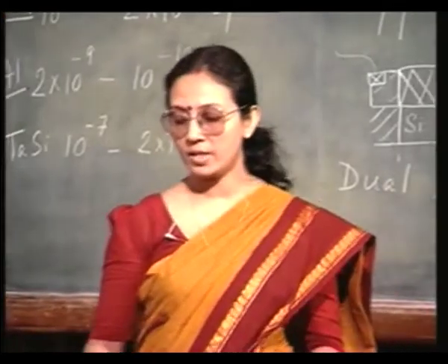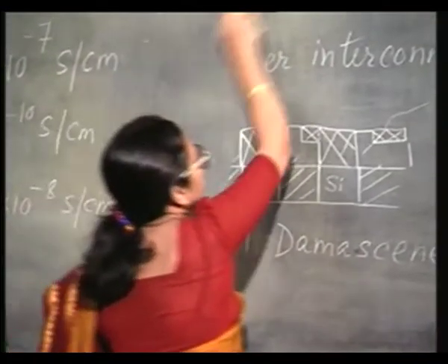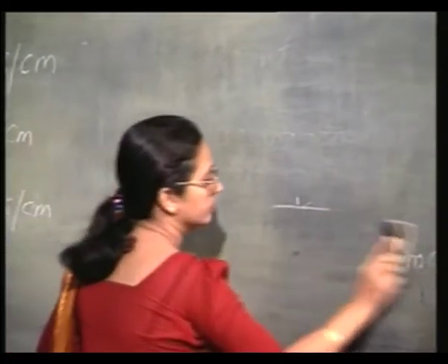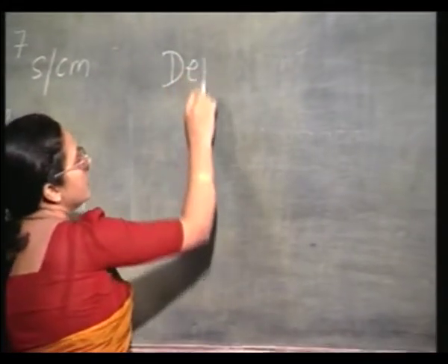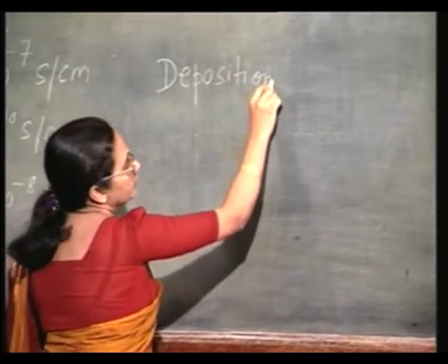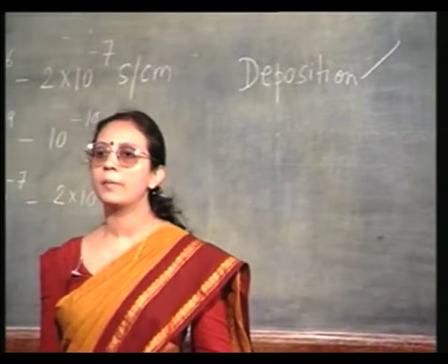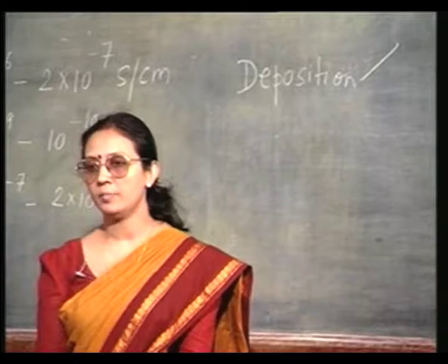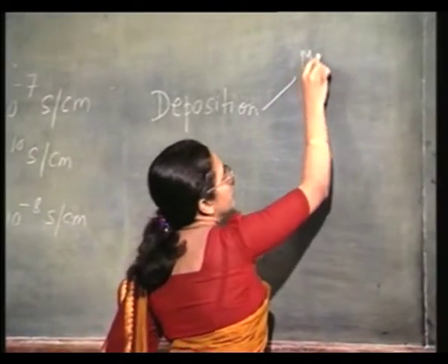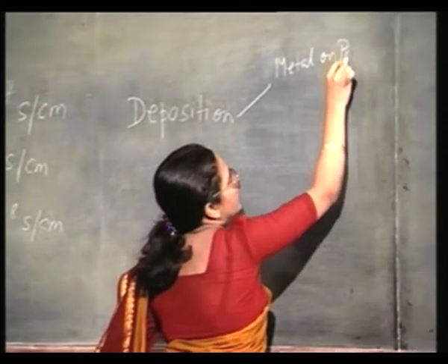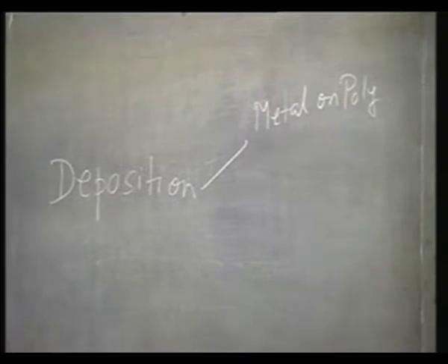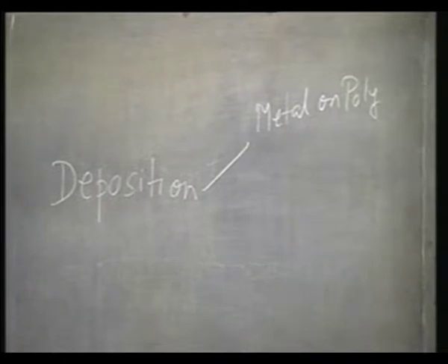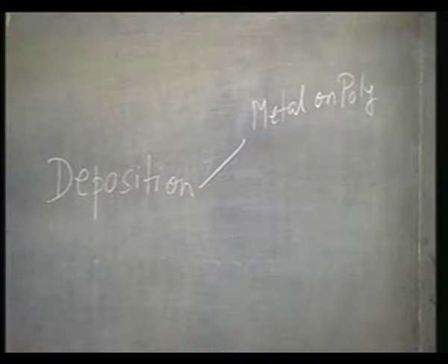There again you have various choices. So, silicide is deposited. One choice is you directly deposit the metal on top of polysilicon. You deposit tungsten or tantalum directly on polysilicon and sinter. You understand the meaning of the word sintering, right? That is, you heat it, you do a high temperature treatment, so that this metal forms a silicide at the region of contact, where the metal and the polysilicon at the interface, it will form a silicide. That is one possibility.